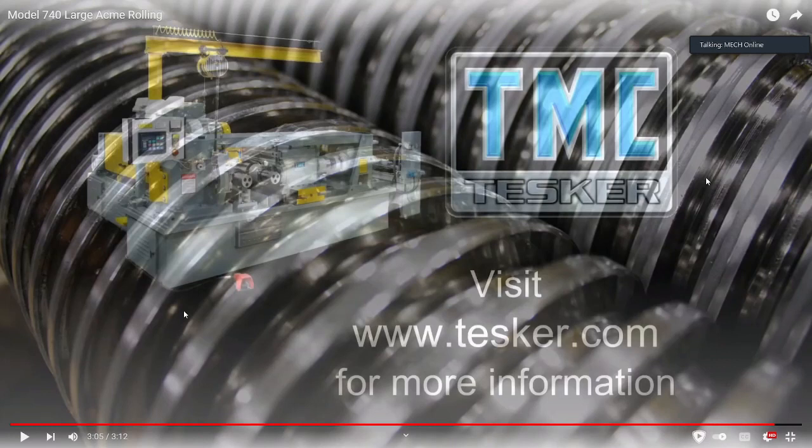If you want to do a thread cutting operation on a lathe, maybe it will be a one shift job, or maybe one shift is not enough, and you need one go, then two goes, then three goes, with so many accuracy checks, and thread gauges and other things will be used. If you do it by thread rolling, it is a cakewalk, like a knife through butter. The only problem is that you need an appropriate thread roll.